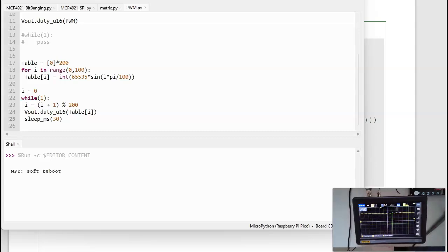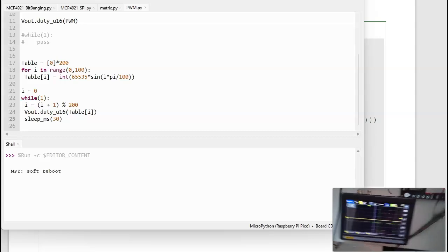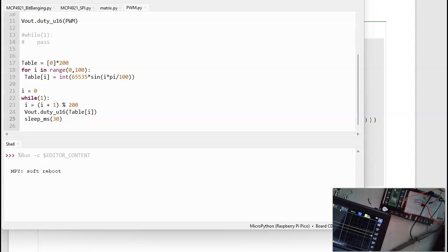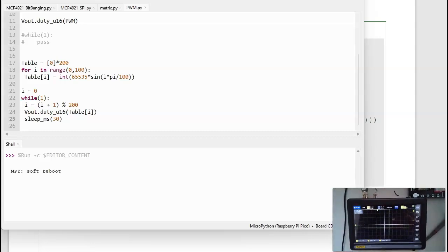Run it through a Butterworth low-pass filter. That's over here. There's my Butterworth second-order low-pass filter. And what you see is a little bit of ripple. That's what's getting through the filter. If I slow it down, you can see the half-rectified sine wave. It's going up, coming back down. I'm bringing down the DC signal. There you can see it. So I have an analog output.